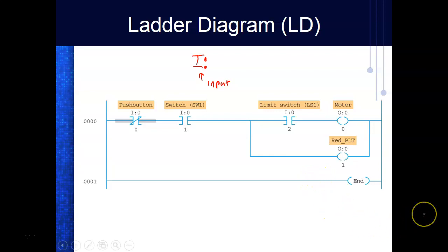I'm going to show y'all, we have ControlLogix, and it's built around a rack-mounted modular PLC. In hybrid PLCs, modular PLCs, and fixed PLCs, the CPU does not occupy a slot. It's inside the PLC, so the CPU is not assigned a slot number.